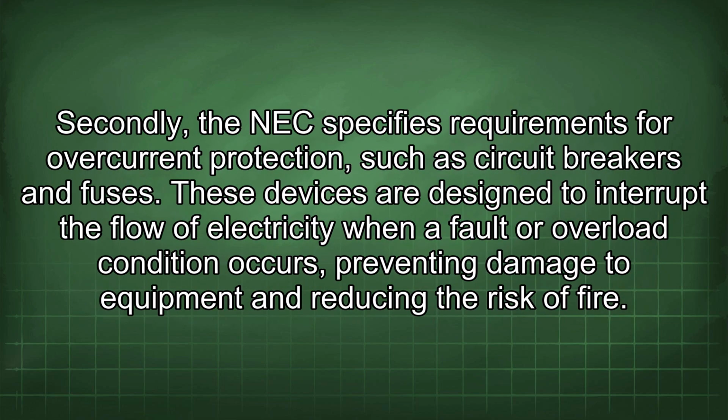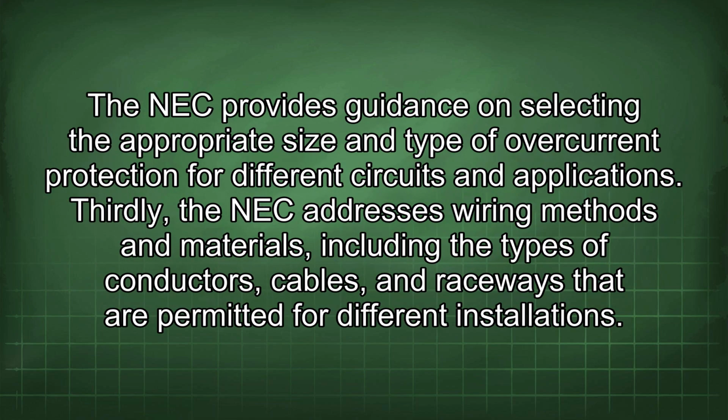Secondly, the NEC specifies requirements for overcurrent protection, such as circuit breakers and fuses. These devices are designed to interrupt the flow of electricity when a fault or overload condition occurs, preventing damage to equipment and reducing the risk of fire. The NEC provides guidance on selecting the appropriate size and type of overcurrent protection for different circuits and applications.